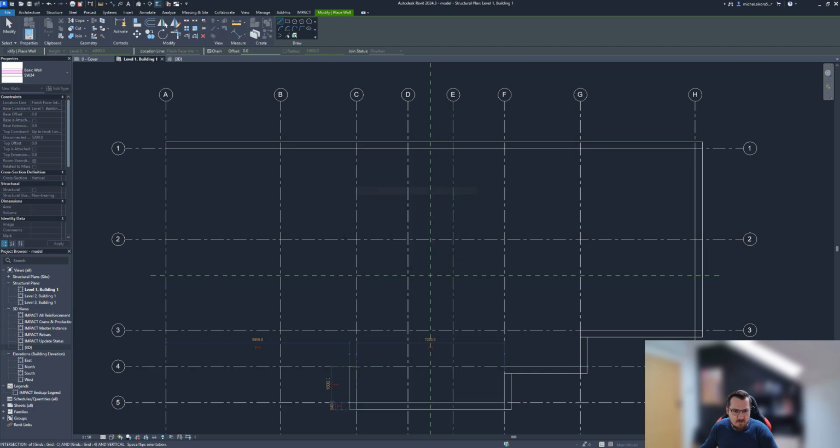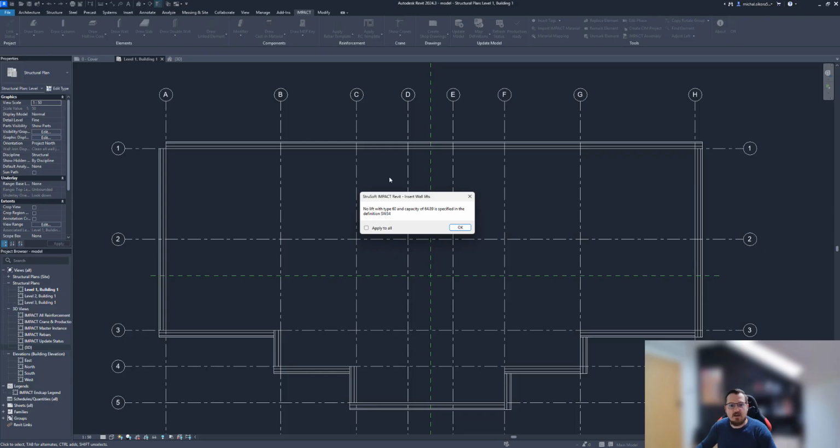You see how fast the modeling itself is. Basically, every single time I do that, Impact automatically places casted materials, properly selects the layers of the elements, gets the lifters in, gets the bracing anchors, etc. However, I will get a warning now once I escape out of that. Impact warns you that this wall is massive. It's 30 odd meters long. It's too big for any kind of lifter that we have defined in the database, and Impact warns you about that. I'm going to take a sip of water.